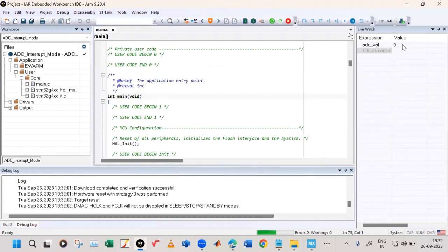Now I will remove it from the ground and connect it to 3V3. When I connect it to 3V3, the value it is showing will be 4095. In the same way I've shown, using gain compensation, it comes out to be 3300. I configured it in that way, and if I don't use gain compensation, it gives the value 4095. Okay, I'll stop this.